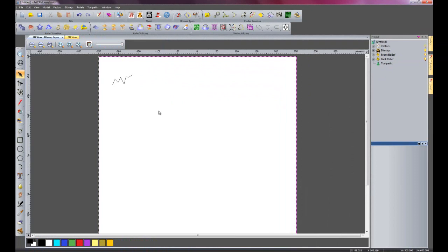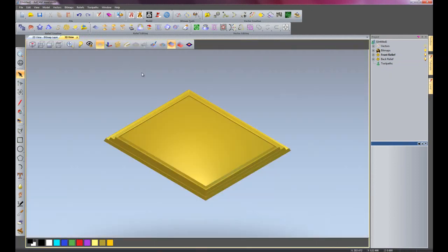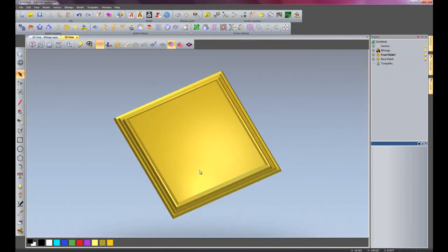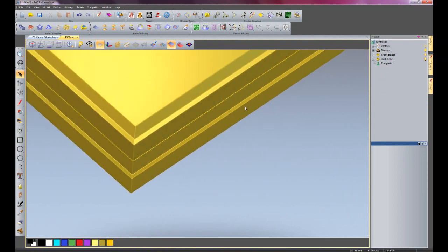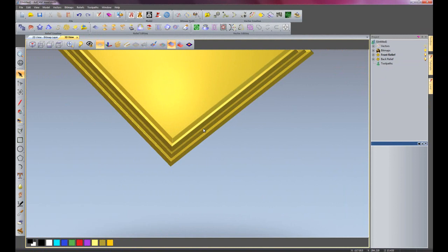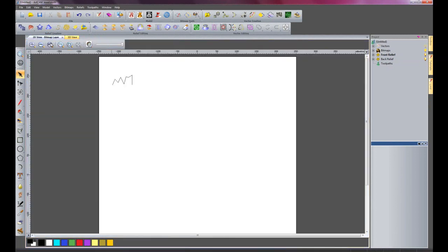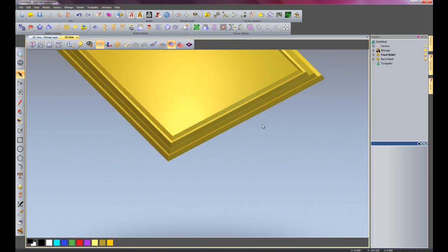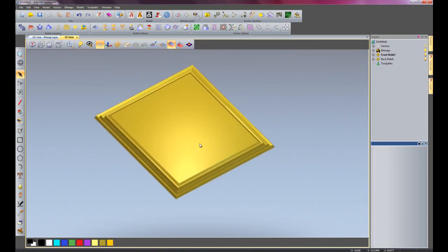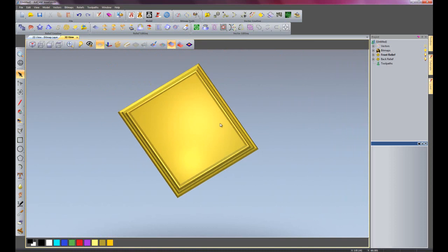and then close my contour blend and go into the 3D view, and I've created this shape, a feature on the outside of the sign. The contour blend would follow any pattern that I put here. I could have put radii on these points and then it would have given the same effect when it created the relief. So there we basically have the base for the sign.